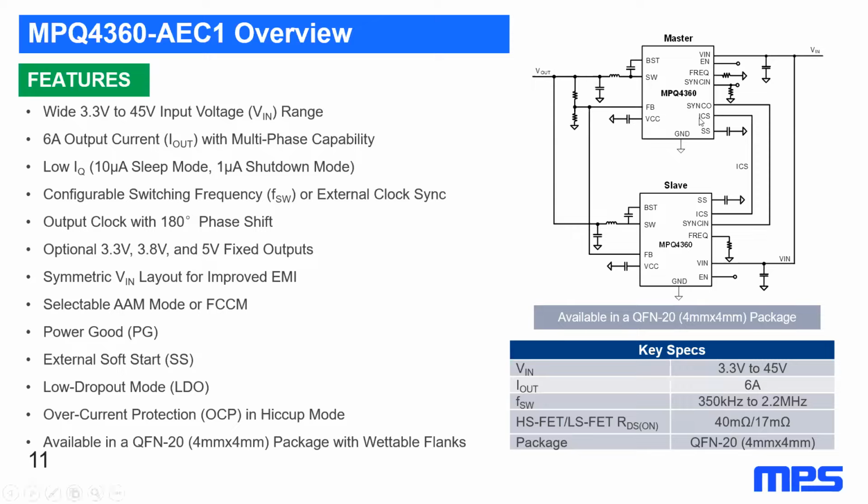Then this part also has an ICS pin, which is used to share the current information, so we can make sure that both phases are delivering the same amount of current. We can connect those pins together, so they will each be delivering half the total output current.